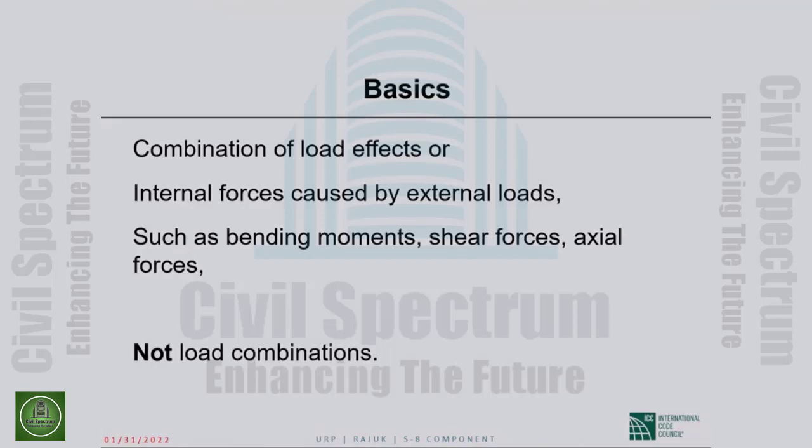And the answer is that we don't. We have never ever combined or even tried to combine gravity loads with wind loads. That's not what we do under load combinations or in design. What we do is, gravity loads, let us say dead loads, cause bending moments, shear forces, axial forces in various critical sections of various structural members.